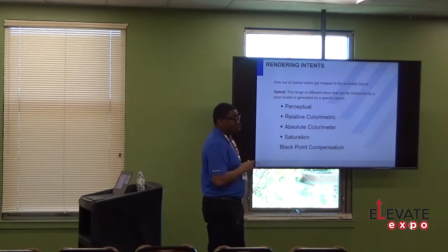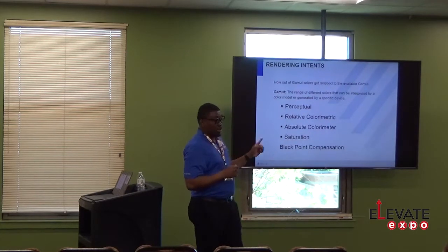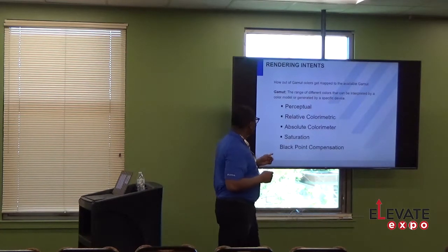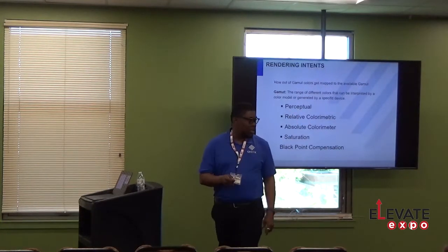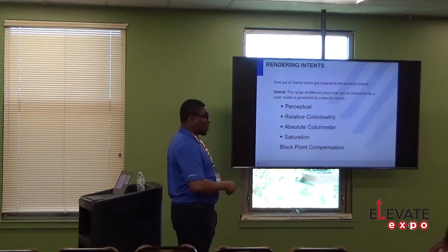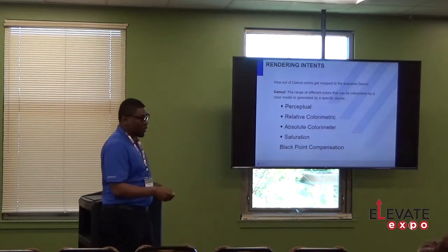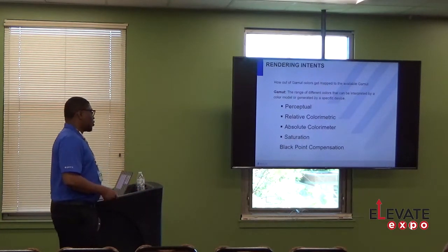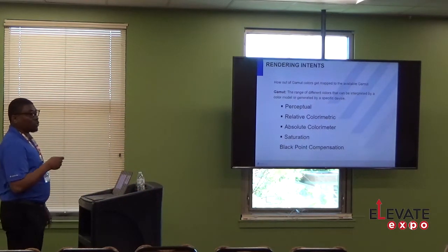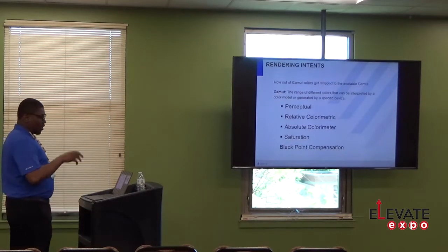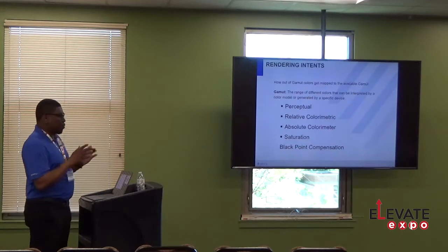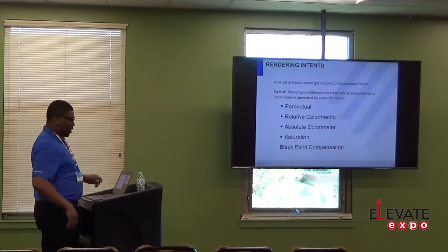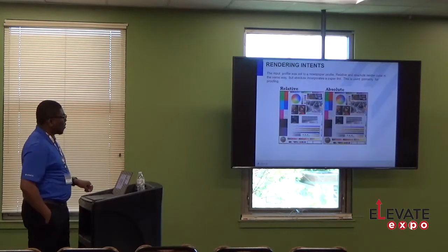Again, this is also another setting in your design software. I believe in Adobe, the default is perceptual. Again, if you are using that same thing, you want to make sure in the RIP software, it is the same exact thing that you're using. So those are the two settings you should check in your design software. Figure out what those are, decide if that's what you want to use, and then make sure that matches in the ONYX RIP software.